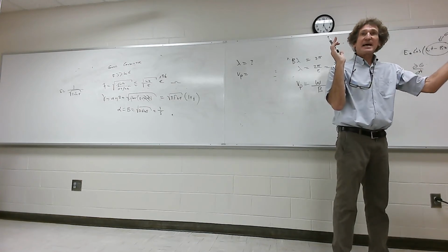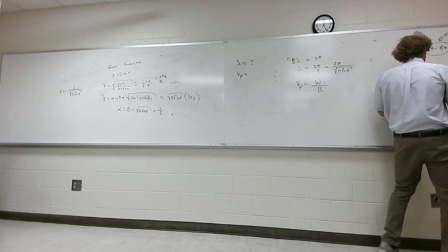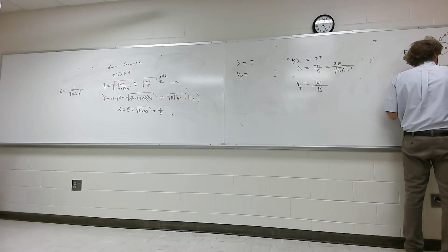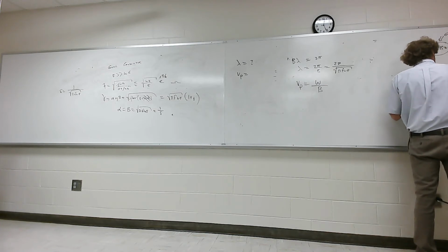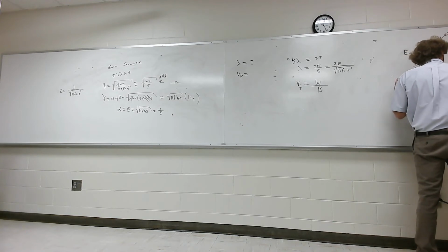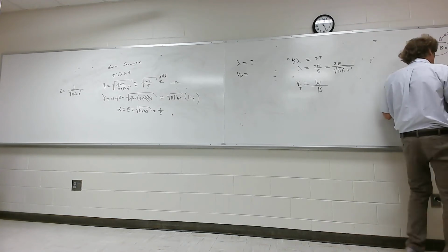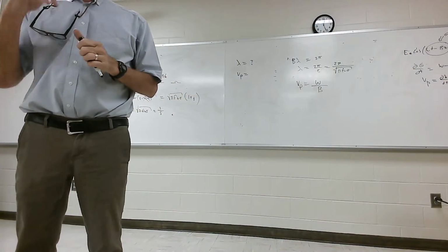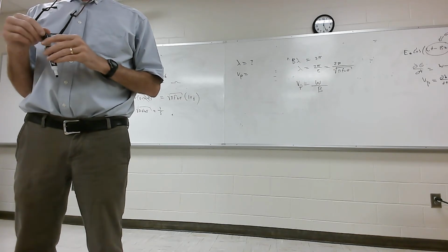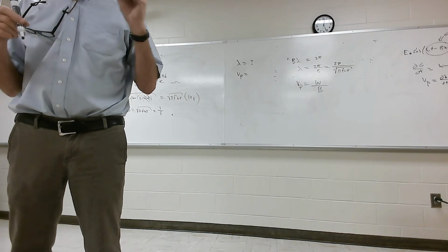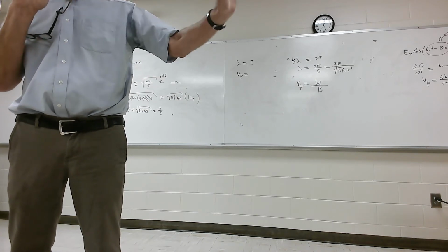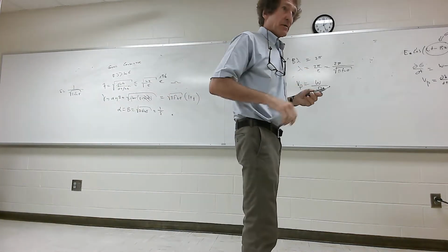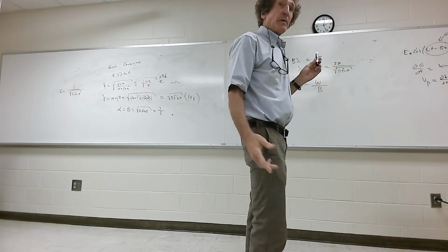You want to see how fast that phase point moves through space. When you do this, you get simply what? Omega minus beta times dz dt equals 0, and that means dz dt is equal to omega over beta, and dz dt is the phase velocity. That's how fast the phase is moving. Now for group, it's a little different. But the group velocity is the velocity of energy propagation. Anytime you have a plane wave, phase and group are the same. That's the truth. But in waveguides, that's not true, and we talked about that. So that's phase velocity. Do y'all remember doing that?